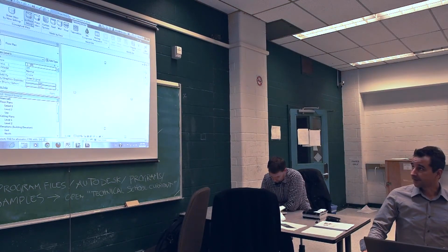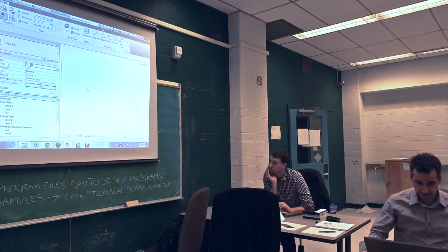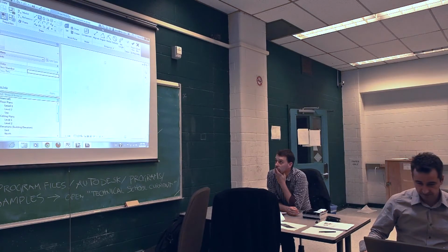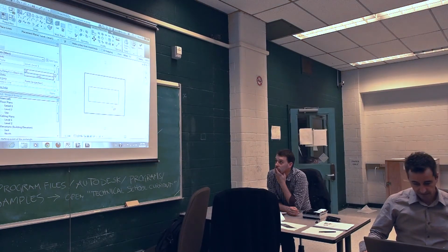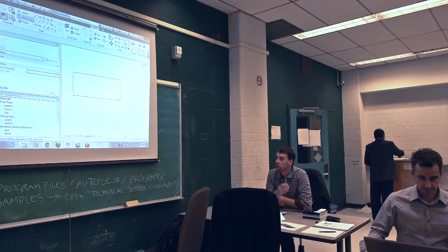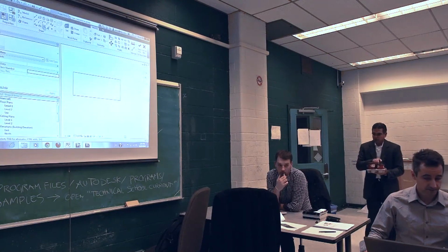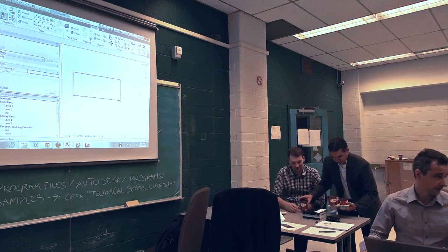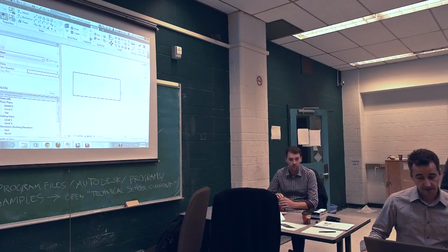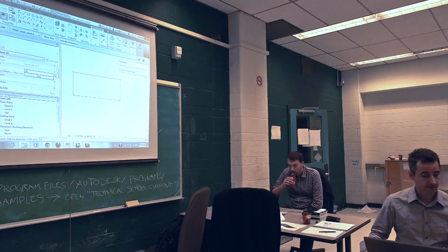So I'll start by doing an In-place Mass. We don't need to get fancy on the names. I have my project set in metric, which is not really important. I'll just create a quick footprint. Once you start Create Mass, you get into this edit mode, and you have a number of editing tools. So I just chose the rectangle and created a rectangle. Don't worry about the size and stuff like that, it's not really important. Once you have a rectangle, click on it so it's highlighted, right?